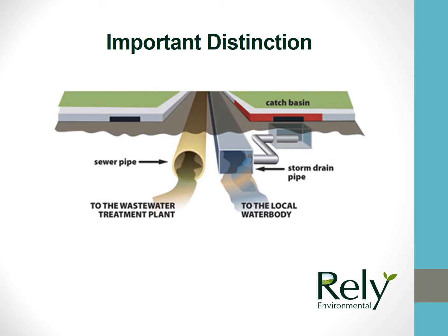Storm drainage systems are designed to decrease the chance of flooding. The rainwater that used to be absorbed into vegetated areas is now collected and carried elsewhere. In urban areas, the storm drainage system consists of drains and underground pipes. Storm drains are normally located in streets and parking lots. In rural areas, the storm drainage system may be in the form of ditches that carry the stormwater alongside a road or a piece of property.